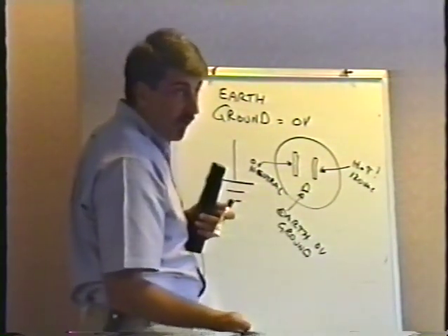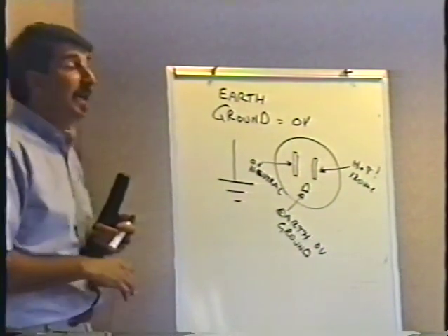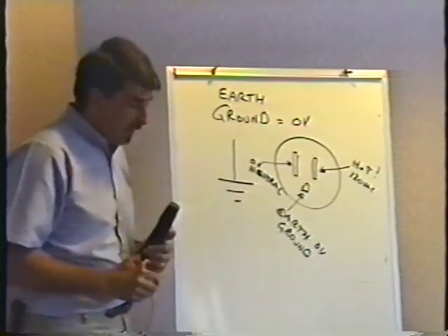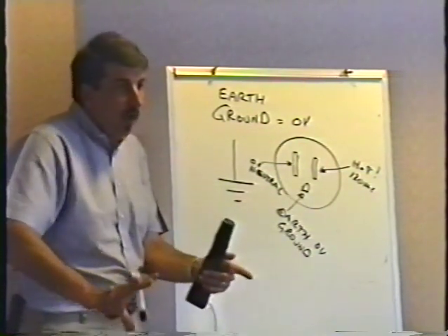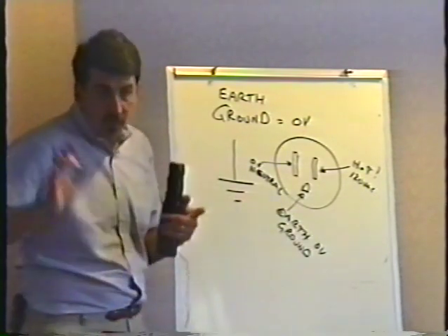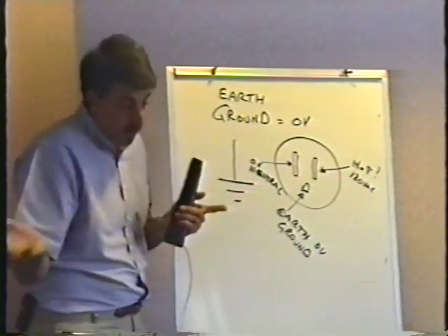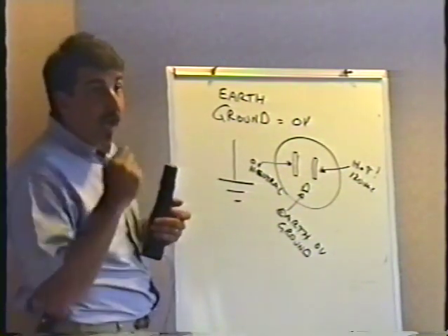It's floating. The ground is floating. This can be dangerous because you no longer have a safety ground, and sometimes the effect will be you'll touch two rails of two different pinballs and you'll get a shock, or even just touch the control panel of a game if you're wearing no shoes, I should say, if you're wearing bare feet, and you might also get a shock.